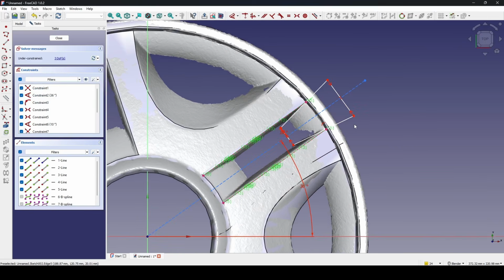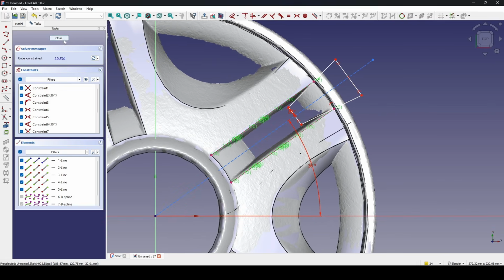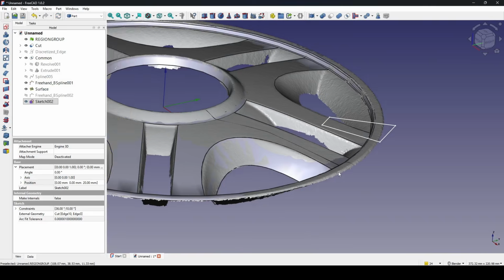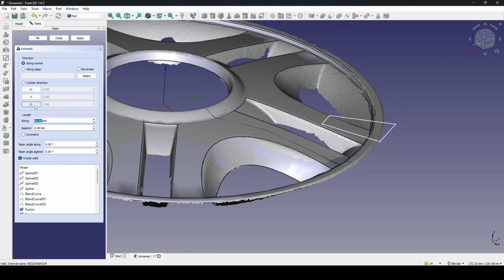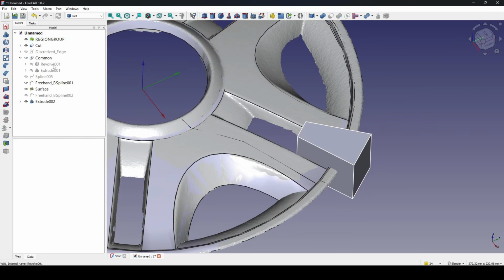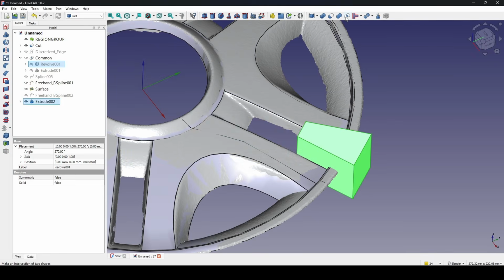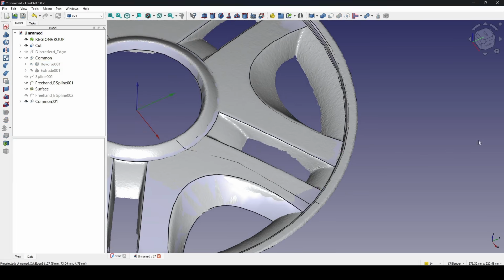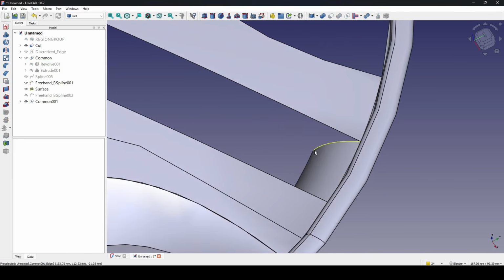Okay, nice. Now we can close it, and I will extrude this one down in the -1 in the z-axis and 50. Now I can control select the Revolve 001 and the extrude, and I go to intersection. Yes. Now if I hide the mesh, you can see I have another surface in here.